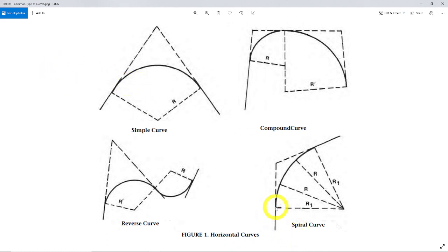They start with a tangent, go into a simple curve to right here where they start into a spiral. Start a spiral, and this section here is the spiral. It's hard to tell on this one, it's a little bit small, a dynamic spiral. It's an ever-changing radius as it goes. So you go from tangent to a curve to a spiral. These happen on railroads especially a lot when they need really gradual long curves that change for such a long entity and with a lot of force.